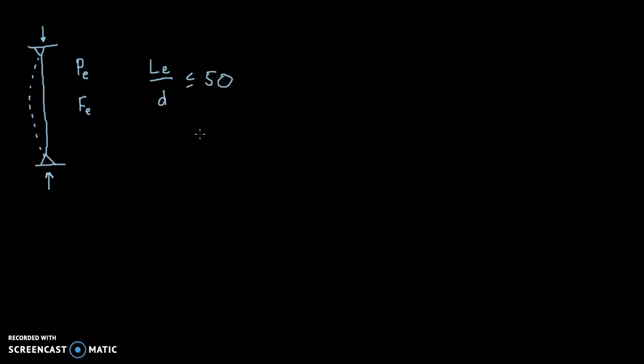So we never want this effective length, which is what L sub e is, divided by d, which is the least dimension, to exceed 50.